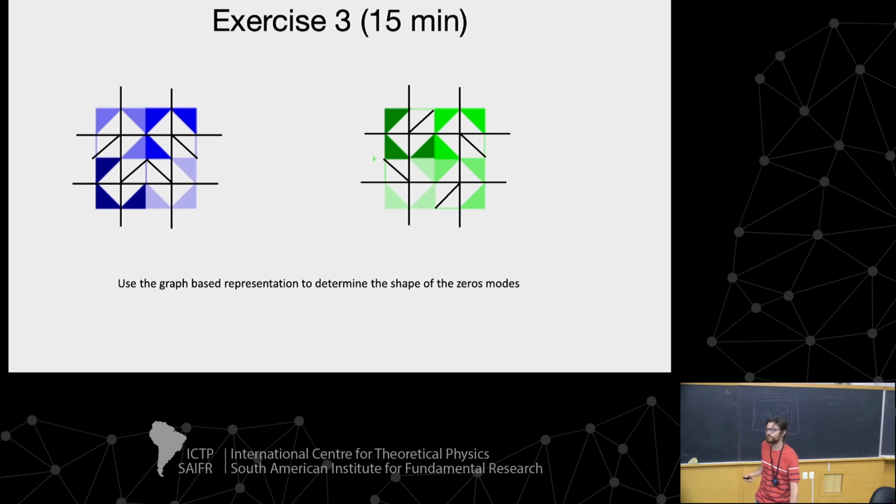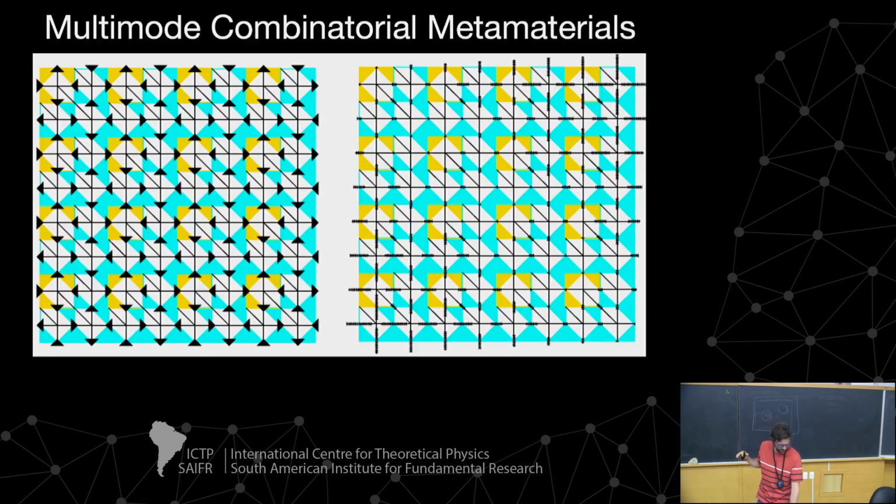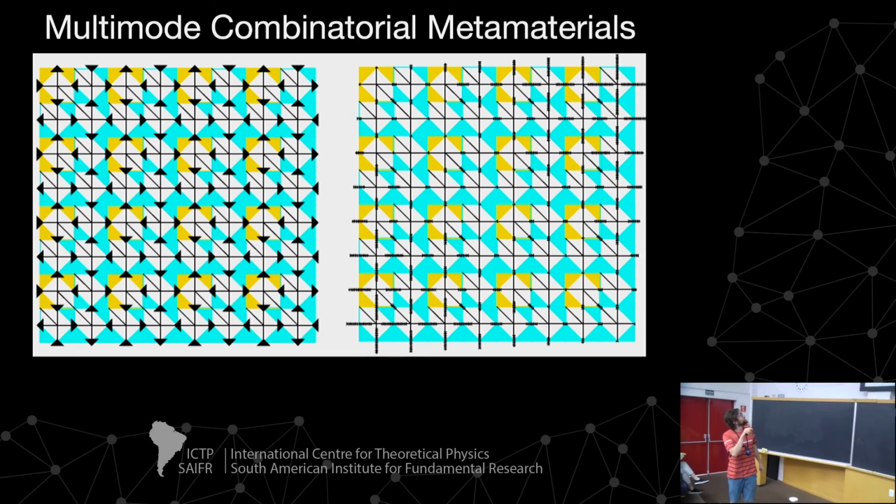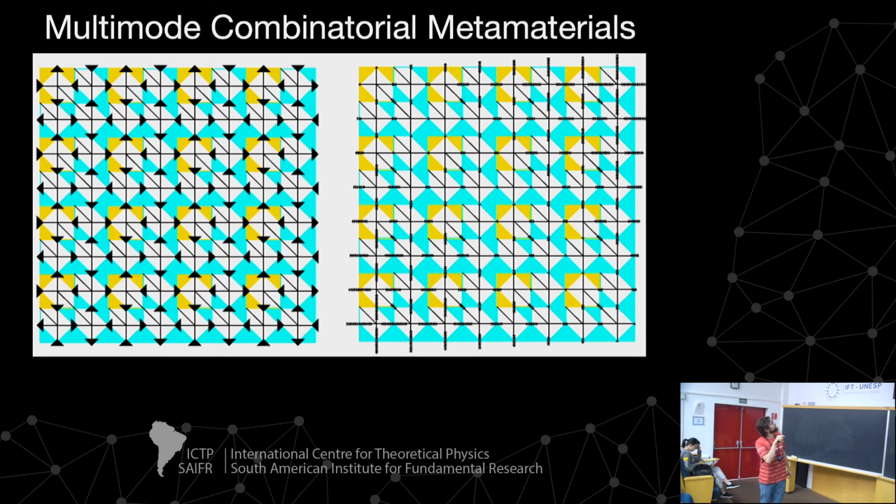What we did is we looked at the mode scaling, and we saw how there's one lattice that has 2 modes, and this was interesting because we hadn't really seen that in the literature before. This one is the rotating square mode, and this one is this weird mode that has a lot of deformation in the corner and in the bottom corner, and very small deformation in this diagonal here.